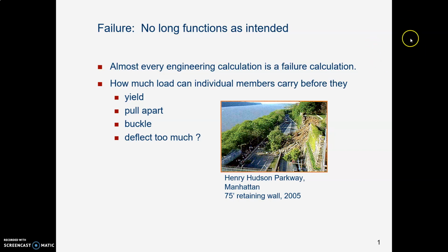When we design things, we are almost always thinking about at what point will they fail? Because once we know the failure point, then we can figure out how we can stay back away from that failure point. So we might be thinking about how much load, and thus how much stress, can something carry before it yields or breaks or buckles or deflects too much.